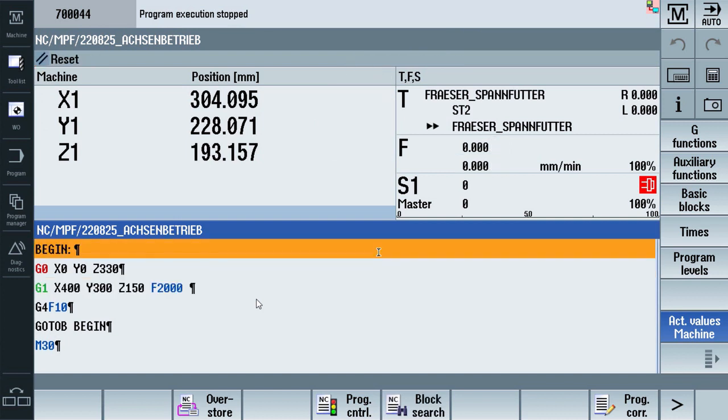In this tutorial, you learned how to work with SINUMERIK low-frequency data, so simple polling operations for reading and writing variables. Also, we talked about how to work with data subscriptions and how to set user alerts on the NCU. The next tutorial will be very special because we will work with high-frequency data coming from the SINUMERIK, and after that you will be able to calculate a floating average over a signal to a dashboard.